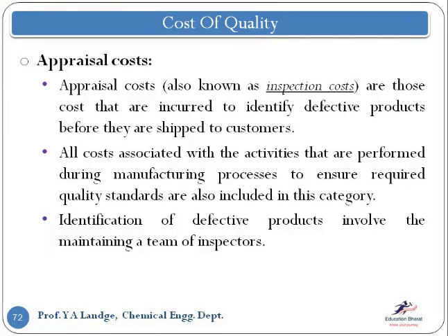Just like in another example that I would like to give, the automobile sector or the mechanical sector, we have a lathe machine that we use, and it is producing some product, some unit. And they always check the diameter and the thickness, all the time using the vernier scale. They check whether there is any defective product coming from the lathe machine. Because ultimately, if there is a small 1 mm gap, or 1 mm reduced or increased, it will not fit with that component in another one. So this is very important to check the quality. It may be very costly for some organizations.